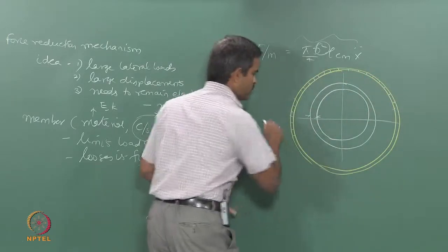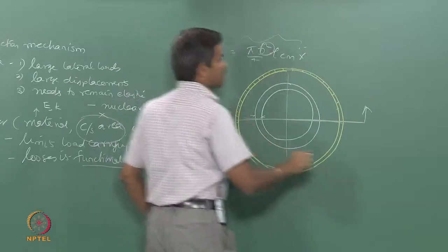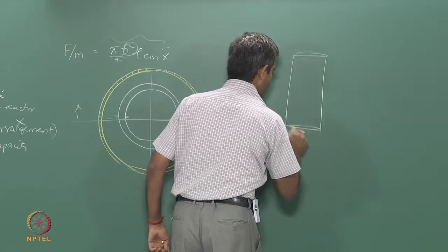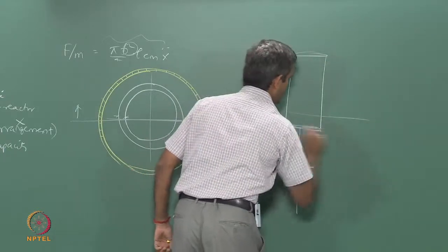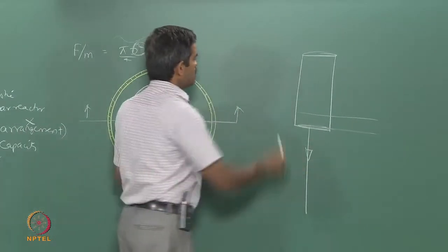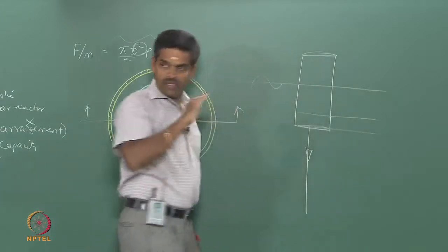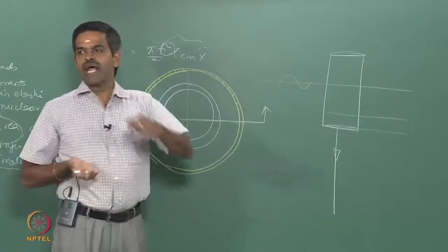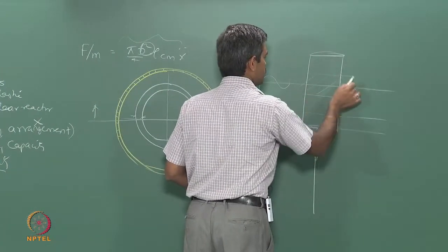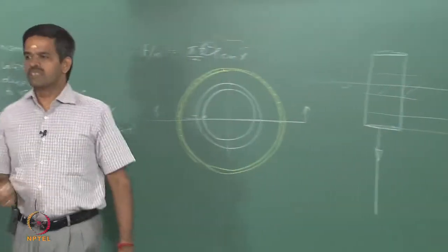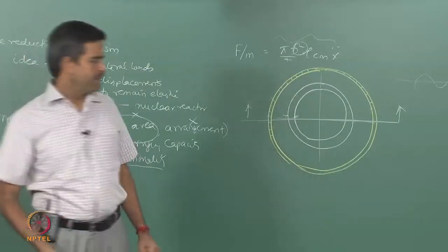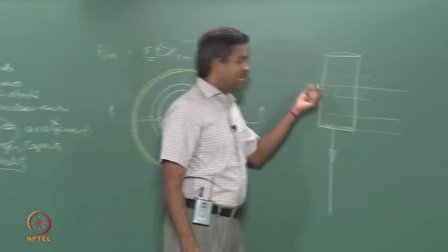If you look at the elevation, let us say I have a cylindrical member. The cylindrical member is actually anchored, because there is a pontoon here, let us say a TLP, it is anchored using a tether and will have an axial tension. Now, this is my free surface or the mean sea level. We know that because of the splash effect of water, this area generally is highly corrosive in nature. The material degradation in this area becomes very fast, about 60 to 70 mils per year, which is very high. Therefore, the material degradation or deterioration is very fast.